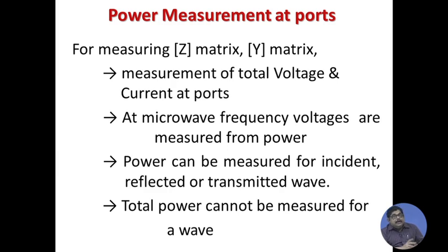Now, think of if we try to measure power at high frequency. Power is either flowing with the incident wave or with the reflected wave or with the transmitted wave. And remember that the superposition principle applies for voltages, it does not apply for power.